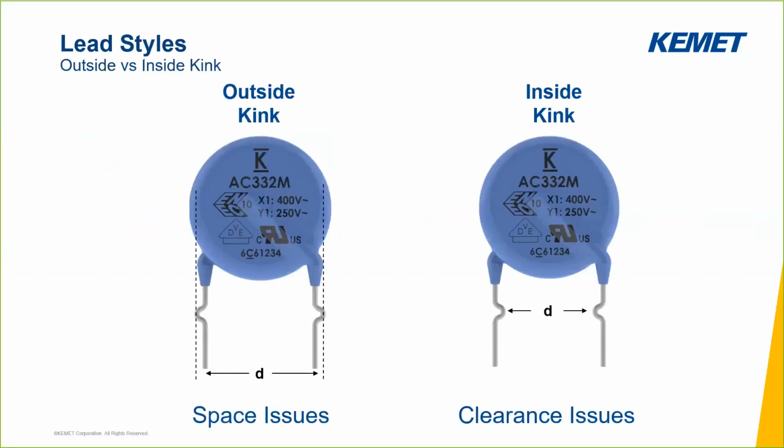Now, when comparing the outside kink versus the inside kink, there are some considerations for both of these lead styles. For the outside kink, on some part types, the distance between the kinks will exceed the diameter of the disc and may cause issues with board space and adjacent components. In this case, designers may want to choose the inside kink to avoid that. Now, when you use the inside kink on some part types, it's possible that the distance between the leads violates the clearance space distance requirement specified in the IEC standard. Users of safety capacitors must consider clearance distances when selecting lead styles to avoid violating the safety standard.